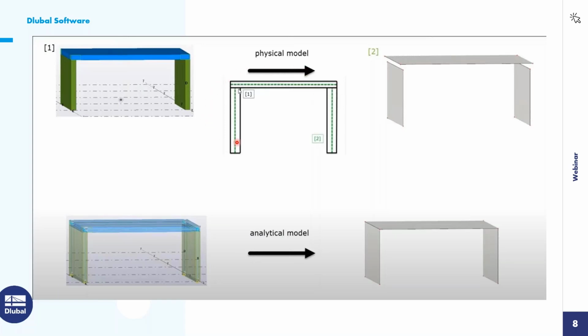And if you would export this physical model, you can see that the axial positions here are not lined up or connected at all. And the wall here is basically just framing into the bottom of the slab. And so there's going to be a space there. And so if you export this physical model, this is what you're going to see in RFEM, which isn't good.